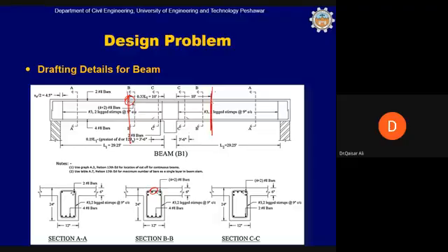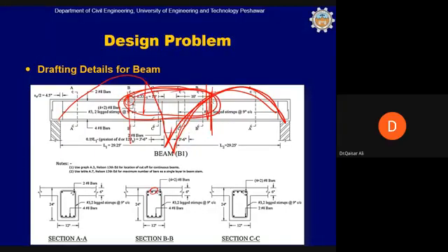If we draw a negative bending moment diagram, it will be like this. I'm sorry, no, it should be like this. Like this. Okay, so you have a negative bending moment only in this region. We don't provide negative reinforcement beyond this location. However, just 2 bars to hold these stirrups will be provided from one end to another end.